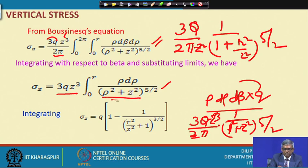Now, by the substitution method, rho square plus z square I can consider as a constant, and that can be further substituted and integrated, putting in the finite integral limits 0 to r, where r is the radius of the footing.